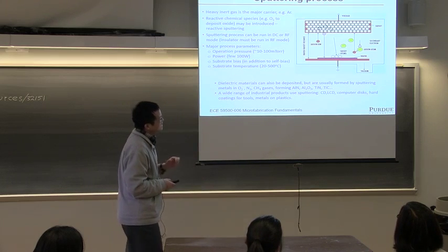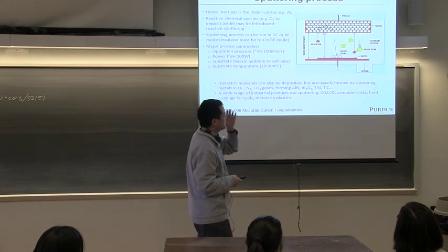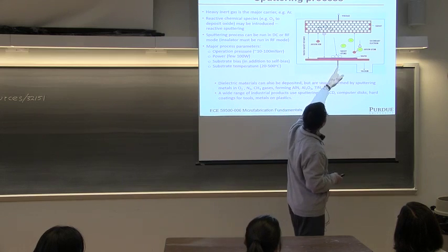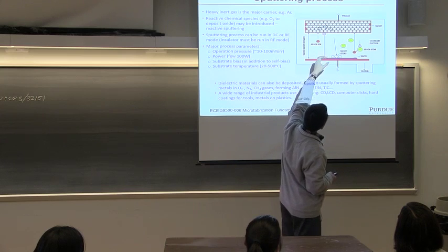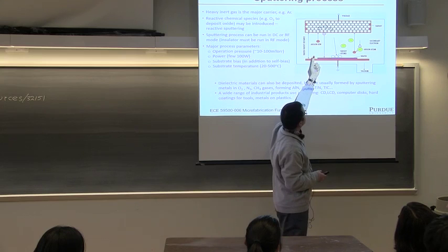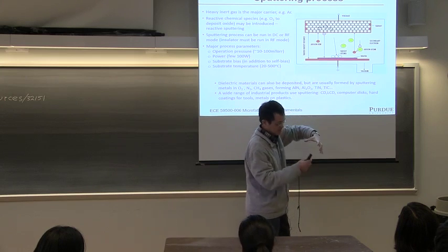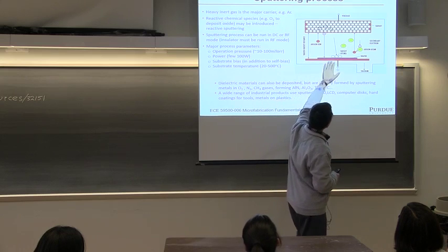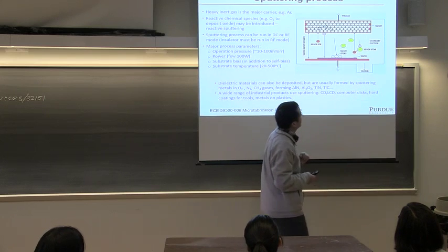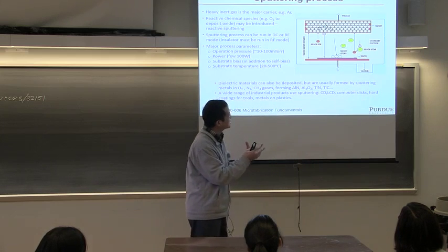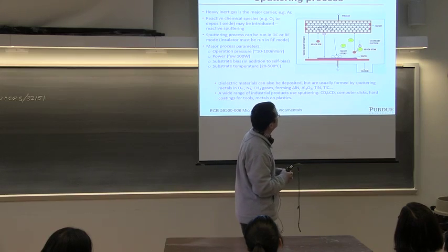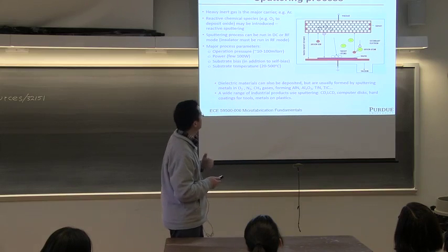So for the sputtering process, as we have generally looked at it, the plasma will generate the red ions, like argon, and the target atoms are shown as hollow white balls. When the ions hit the target, it will generate a lot of dust, and the dust will contain the target atoms. But you can also have the argon ion receive an electron and return to its original atomic state. And then you also have the secondary electrons, and so on.